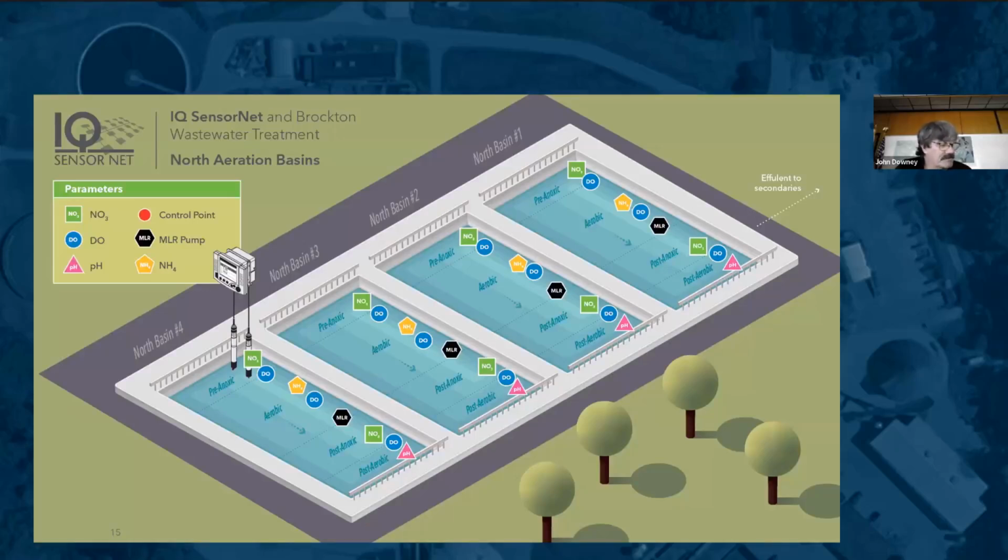As we've mentioned, there are 7 aeration basins here. So normally the total influent is split among all of them. During construction, 1 or more basins were always offline, meaning that the same flow, the same loading was being distributed among fewer basins. That is, the same amount of ammonia is going into fewer basins. Now, why does that matter?